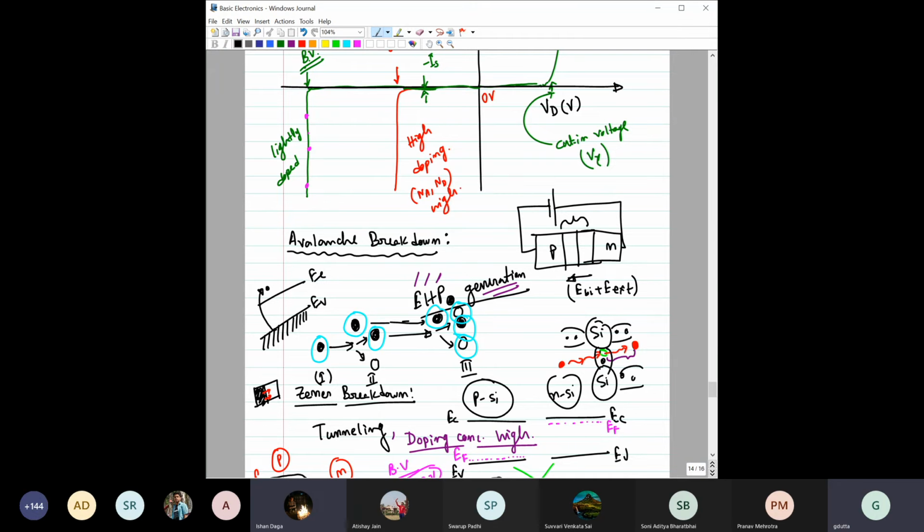No, actually, I think I get your question. Even though this depletion region is quite thin, and it also depends on the doping concentration, this depletion region can generate a sufficient amount of electron and hole pairs to cause the breakdown. To say it simply, it is like this. And if you want to know a little bit more, then I can tell you a couple of things.